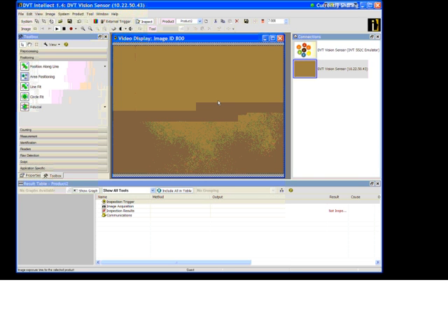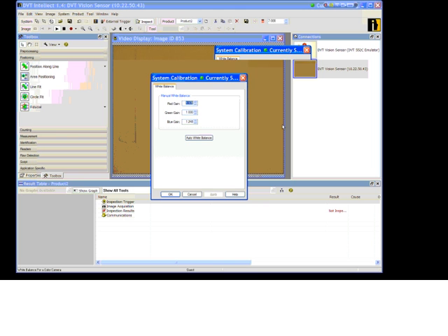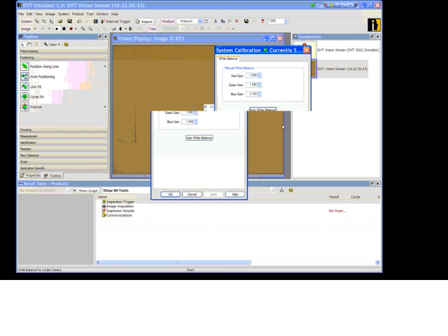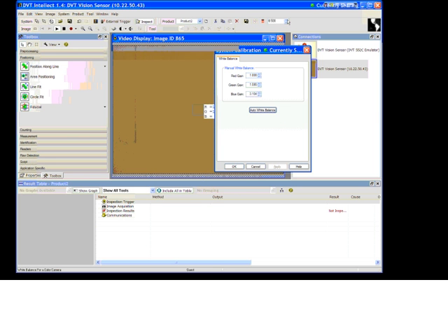And I'm going to go back, and you can see that the blue content is lowered. That's because we had to change the gain of the blue channel to adjust for the light for the white CCD when we did the white balance. So we know we now use a different lighting source, and you see that you need to do auto white balance again. So I'm going to do white balance here, and we get, again, a consistent red, green, and blue value.